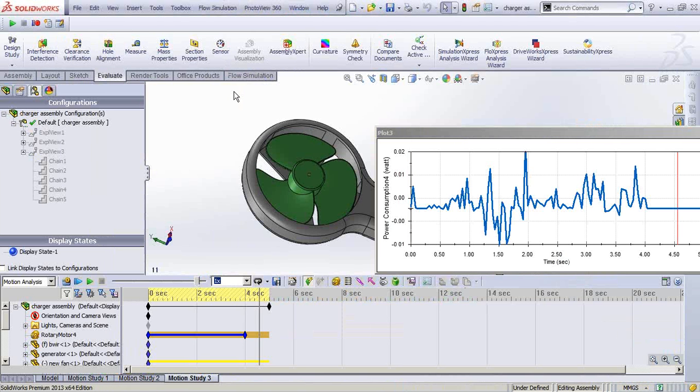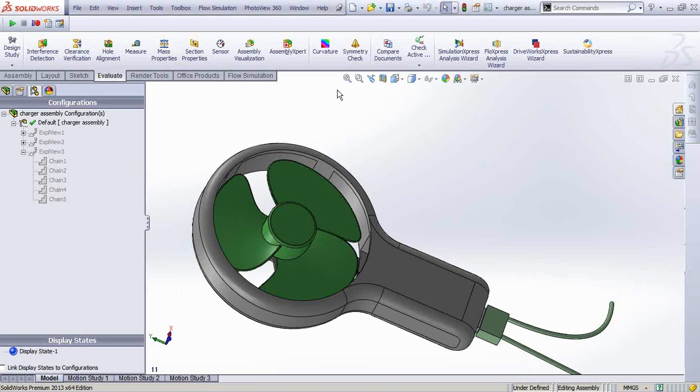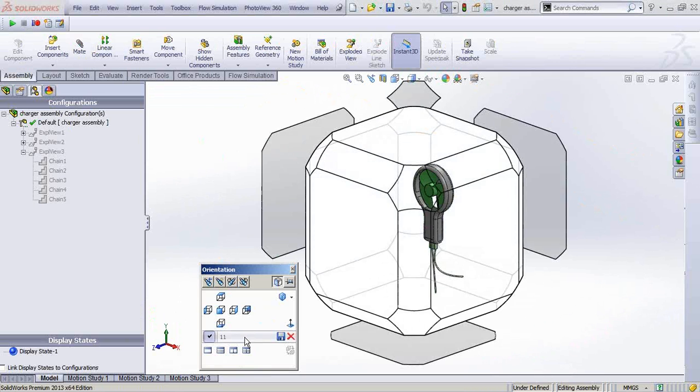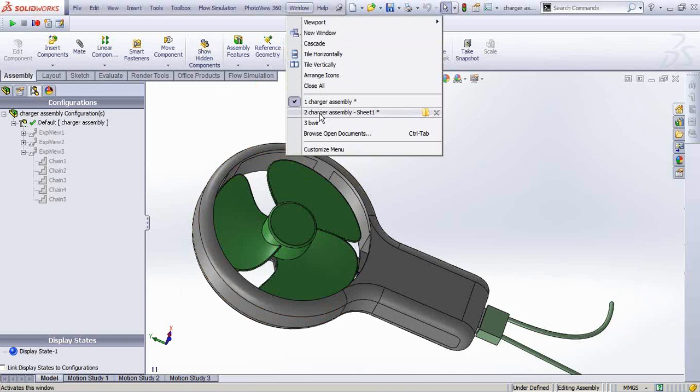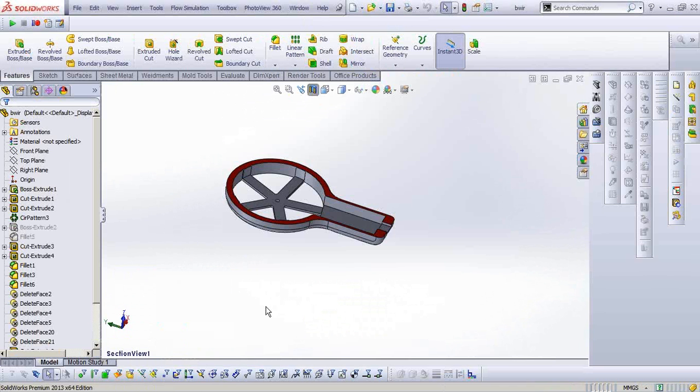Points to remember. Manufacturability of design to be checked. Take my model as an example. The outer casing that I designed cannot be manufactured if it is a plastic component. So I am splitting these components into two pieces, which makes manufacturing easy. Availability of ready-made or standard components to be checked.